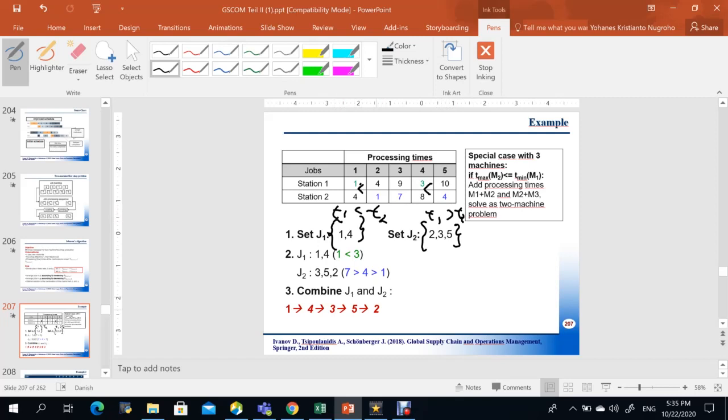And then for set 1, for instance, the job sequence will be job 1 followed by job number 3, because job 1 needs a shorter period to complete. And also for set number 2, we have the reverse situation. The sequence is 3, 5 and 2 because job 3 takes the longest period to complete. Using this strategy, we can minimize idle time due to waiting for the second processing time, in this case painting, right?